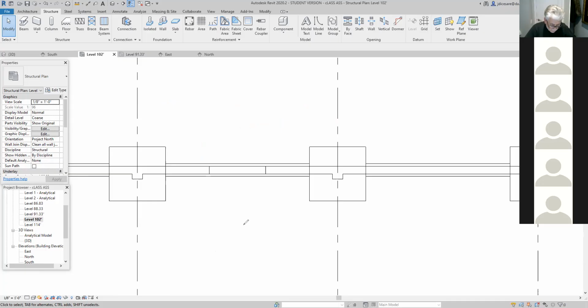So if I look at section EE, here I have elevation 102. And they tell me that the top of that wall is starting at 8 inches below it. So I'm going to use 102 as one constraint, the top constraint, and then I'm going to have an offset of -8 inches. And that's going to put the wall there. And after that, I keep looking.